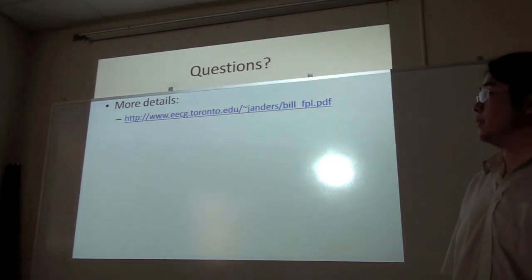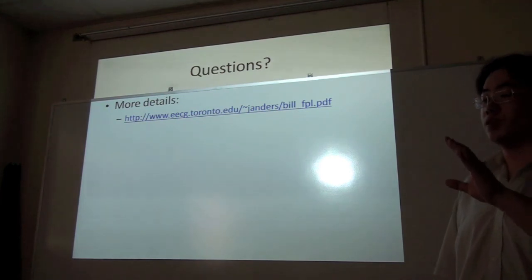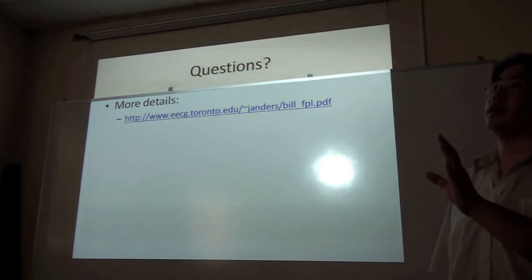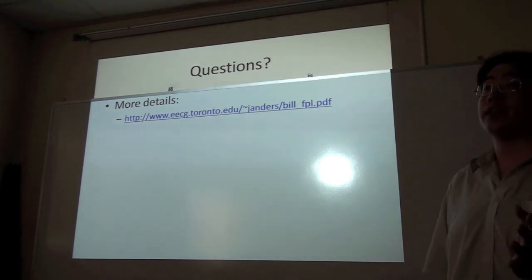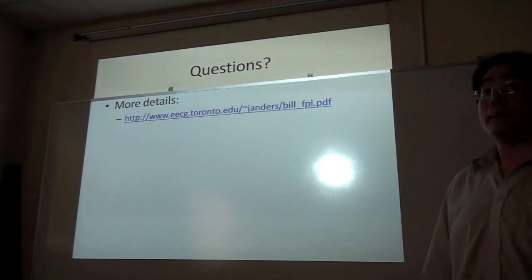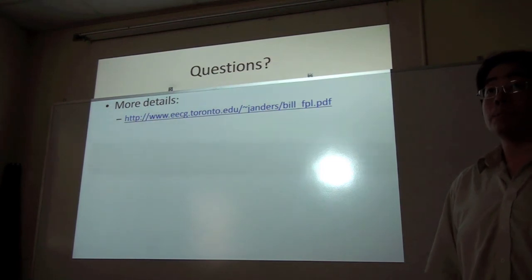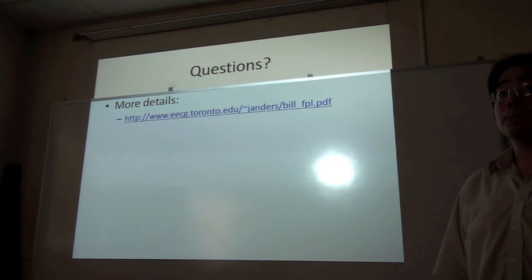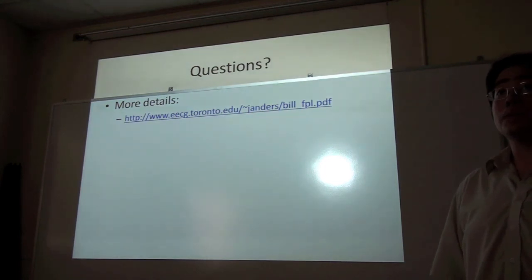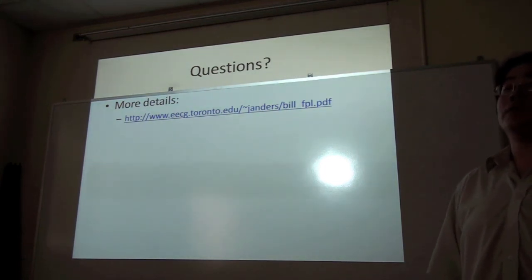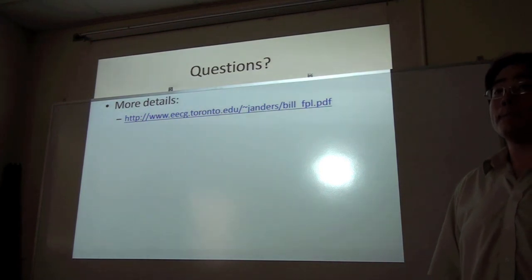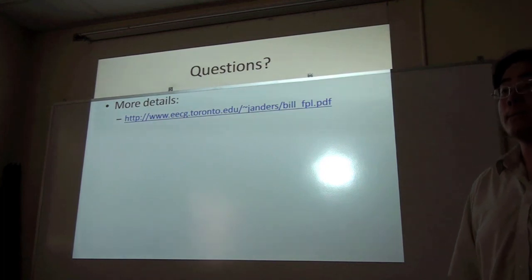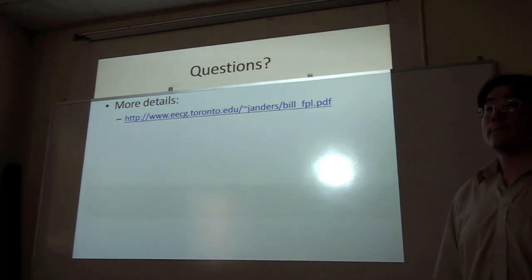Yeah, that's definitely true. We did this in the context that we assume that the circuits are all single clock, and then we asked, can we still use a single clock and get something out of it? He's not generating extra clocks, though. He still is sticking with a single clock, just choosing a duty cycle for it and choosing some storage elements to be latches. But one approach is you could run multiple extra clocks with different duty cycles, and push the right duty cycle to the right storage element. That is a distinction: there's just not going to be one clock in the design.